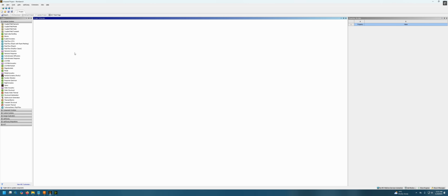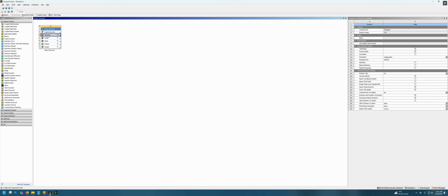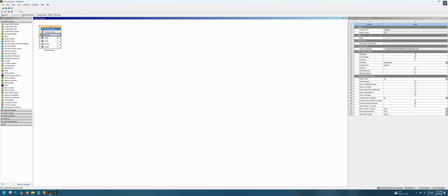So, get the free version of Ansys, start it up. On the left here, go to Static Structural, drag that over into there. Then we want to import geometry. So you right click on that and you can import geometry. You can either browse, or since I was doing it a few times, it's in the list of previous files.